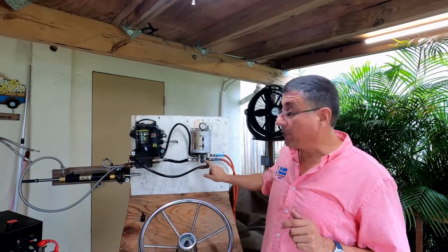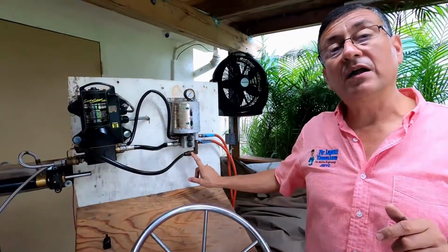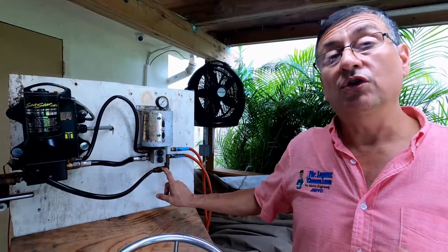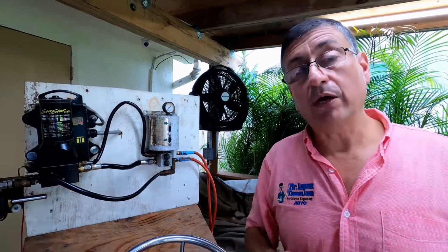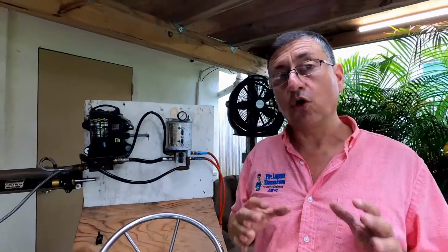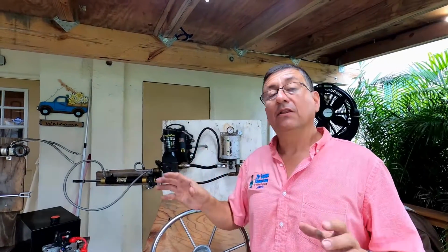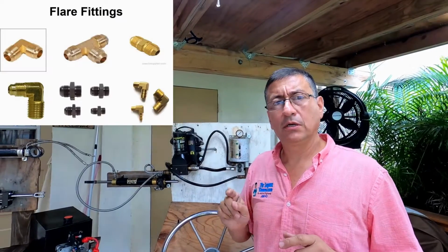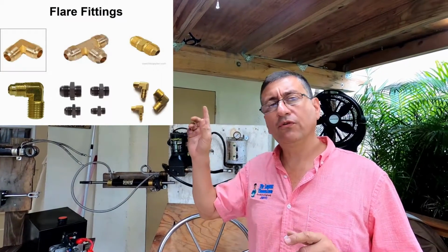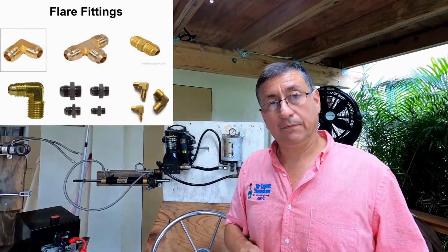In this particular case, for example, the body of valves of this equipment is in aluminum and those fittings are in naval bronze. If you use regular brass, immediately the aluminum is eroded. We are going to study in our course of corrosion that phenomenon. Okay, don't forget the line should be marine lines, approved lines, the fittings, all the fittings, these elbows, reducers, those fittings should be always marine grade.